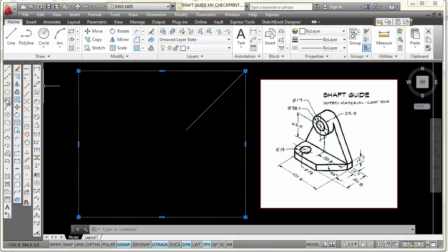I started the rectangle command, and after I picked on rectangle I was prompted to locate the first point, and I typed in 75,75 for that first point. So that was an absolute coordinate, so relative to 0,0, that was located 75 on the X and 75 up on the Y. And after I had entered and located that corner, I was prompted to define the second corner for my rectangle, and so I typed 200,175. So the size of this rectangle is 200 millimeters on the x-axis and 175 on the y.